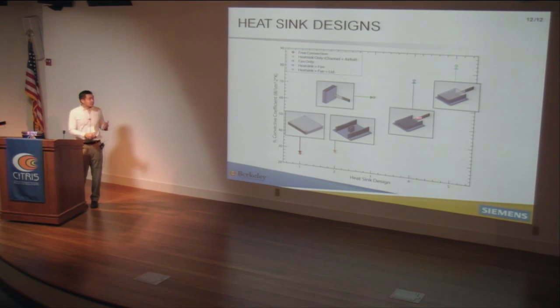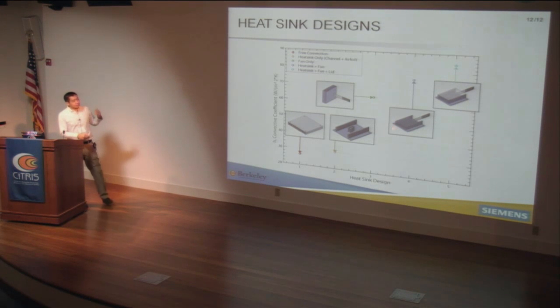With a heat sink, which looks like your standard fin sink, and the fan straight against it, you actually get some improvement. However, we noticed that most of the flow was going along the sides of these channels with not much flow going down. So while you're constraining the flow that was leaving the plate, you weren't getting anything towards the center.